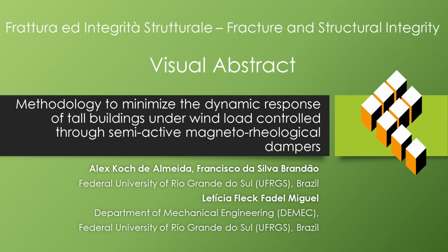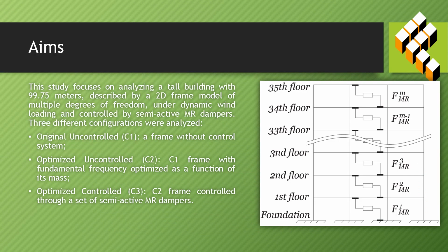Methodology to minimize the dynamic response of tall buildings under wind load controlled through semi-active magnetorheological dampers. This study focuses on analyzing a tall building of 99.75 meters, described by a 2D frame model of multiple degrees of freedom, under dynamic wind loading and controlled by semi-active MR dampers.